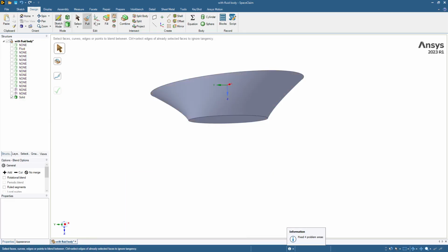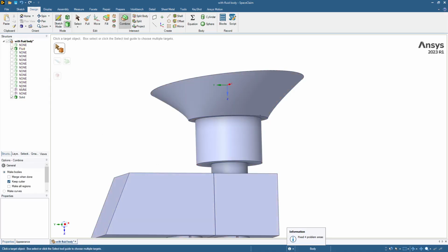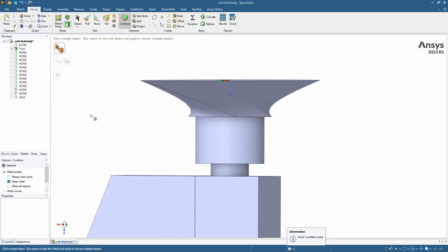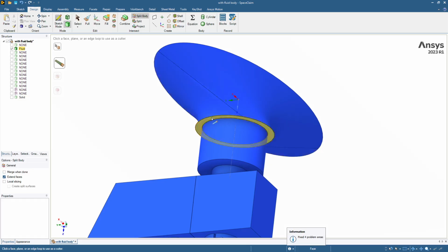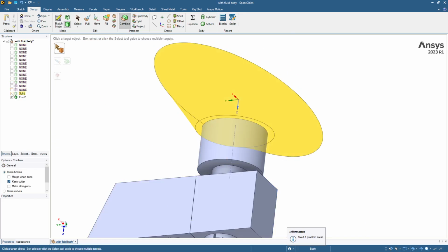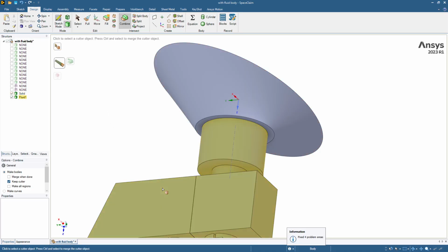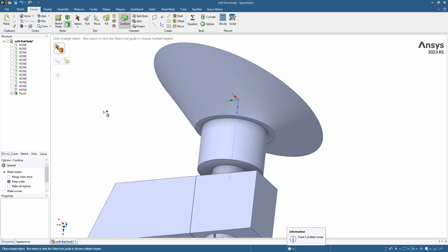And we can take the fluid. We can use the combine tool and turn the combine tool on, and we can first cut off the misshapen one, which is this, with the split body, split this body on that face and delete the defect, and then use the combine tool and turn the solid we made on, and then combine this body with the control key, add this in, and this is our new fluid body.